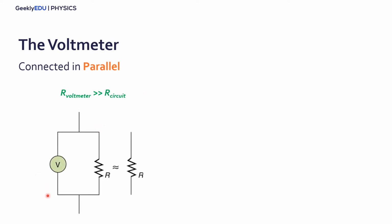Imagine we have a circuit like this. We add the voltmeter in parallel to the resistance, for example, but because its resistance is much higher than the resistance of the circuit, most of the current will flow through the resistance of the circuit, okay? So we're not altering the circuit.